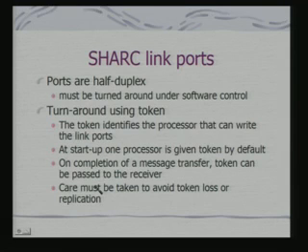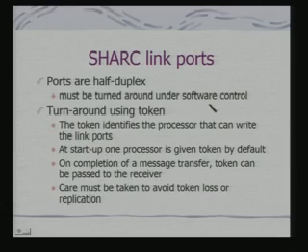These link ports are typically half duplex, in fact for SHARC. So, that means one of the processors can transmit along a link port and the other processor is expected to receive data on the corresponding link port. Both of them cannot transmit simultaneously. So, we need to turn these ports around. That means the modalities of operation of these ports have to be changed, and this change has to be done under software control.